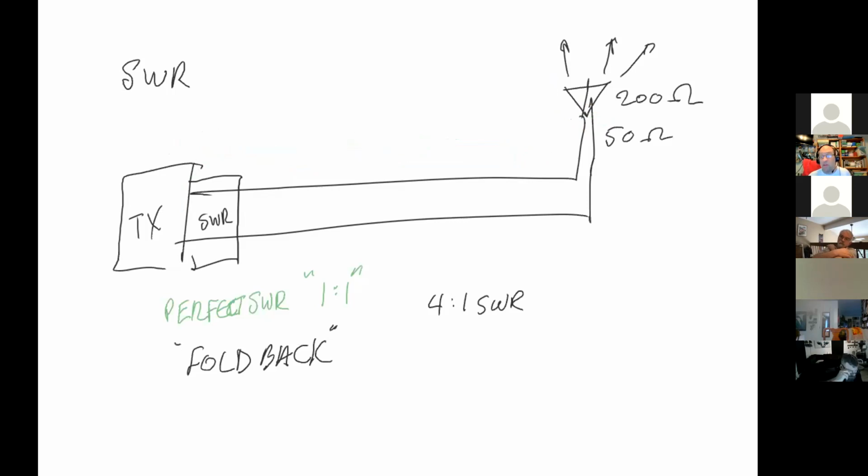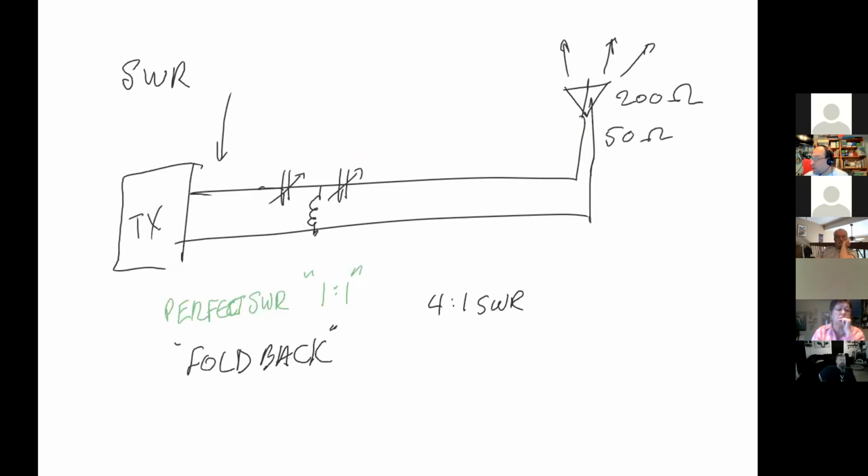I actually have an external meter and an internal meter, because I have my external meter built into an antenna tuner, which looks like this. For us beginning radio people, should we have that set up? I think it's very important to have one, because it allows you to really get an understanding of what's happening. Now, if you get a radio that has an internal antenna tuner built in, typically those will only tune an impedance mismatch of about 3-to-1.